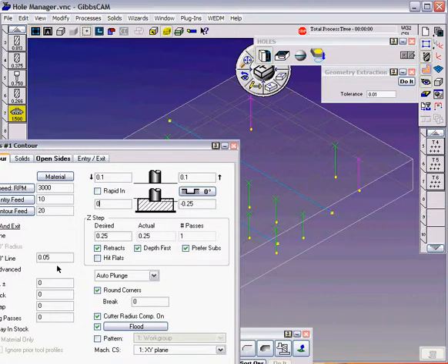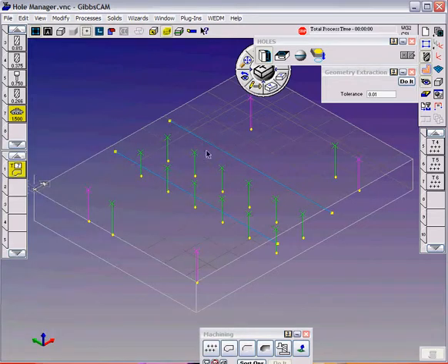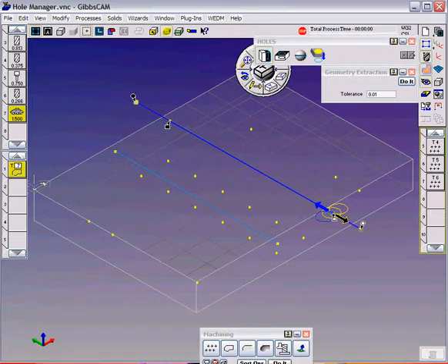Let's give a 90-degree line of 50 thousandths to turn our cutter comp on, so we have the ability to control the speed or the cutter comp, so we can offset the tool and get control over sizing here. Since these are open terminated shapes, all I need to do is click on the open end of the button, and it automatically creates my start feature, and drag the end feature off a little bit as well as the start point. Make sure it says do it.